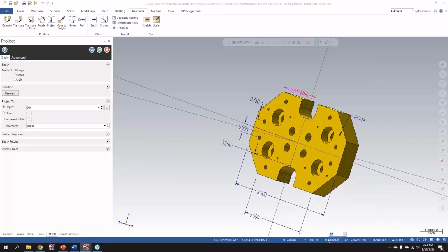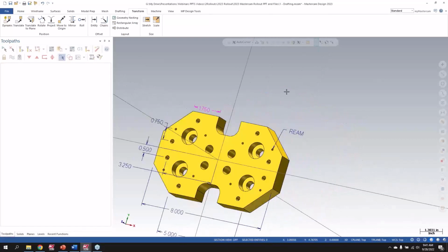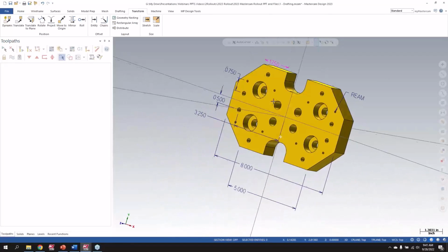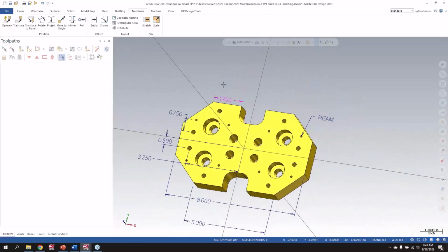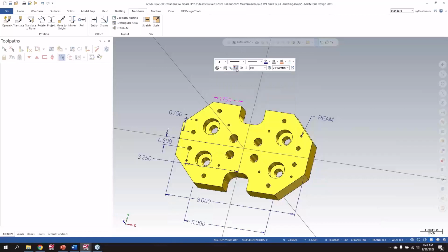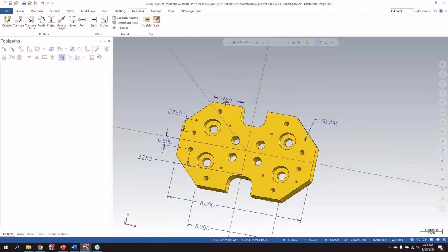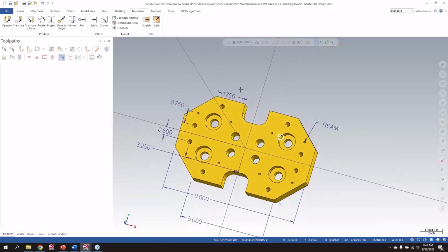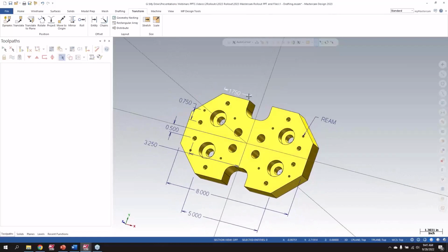So always remember this Z height control, and if I switch it to 2D, I can force anything I'm creating at a specific Z height. It's set to copy here. I could switch it to move, and then it'll move that dimension. And like any sort of transform, red would be the original and pink is the result. So I can always right click, get my attributes manager and say clear colors, and it'll return back to the color the dimension was before.